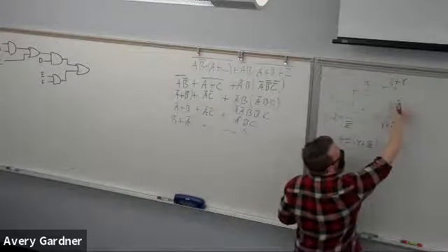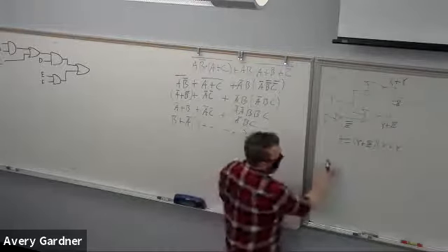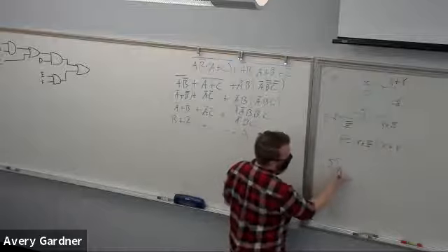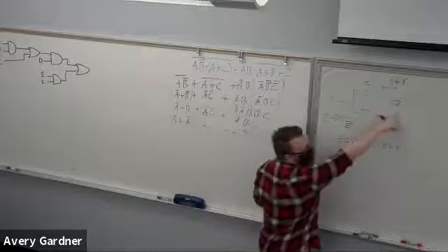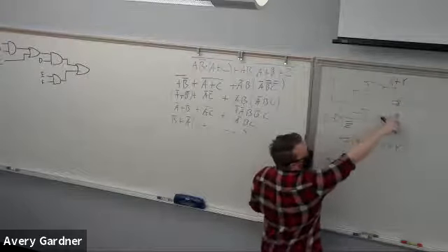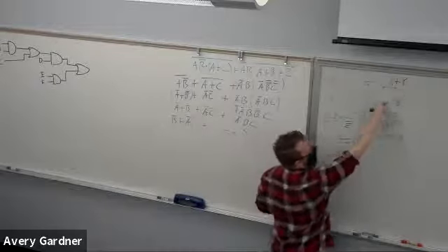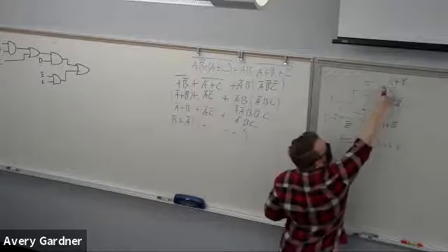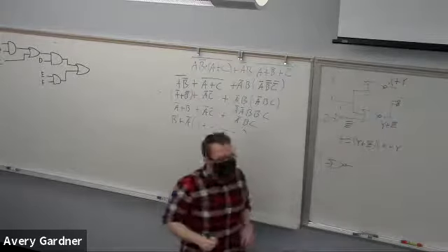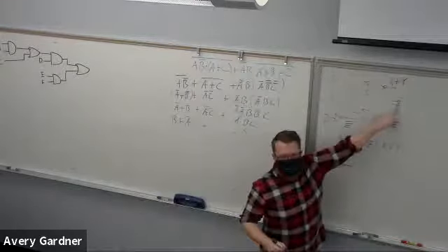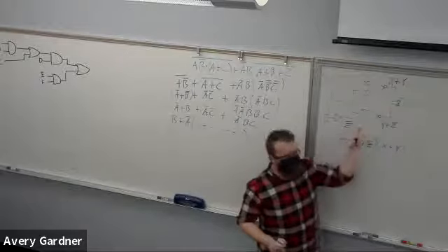It's a NOR gate just by doing those two bubbles, because a NOR gate is equivalent to that. Okay, but I've just ruined this net, and I fix it by pushing another bubble here. Right, because if I do not, it's equivalent. I haven't changed anything, but I've changed the type of gate that I'm using.